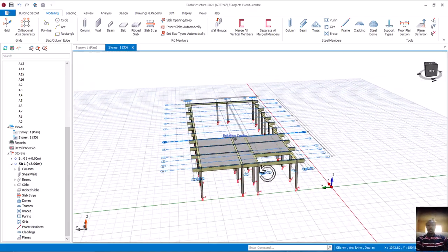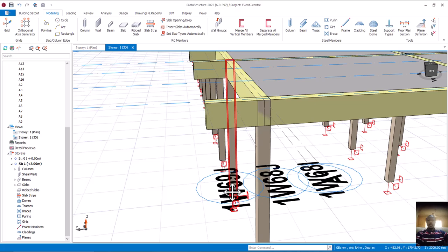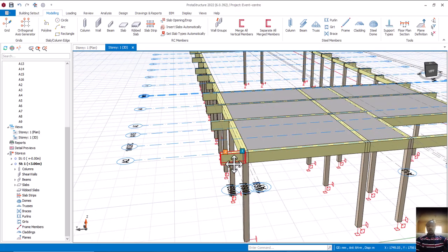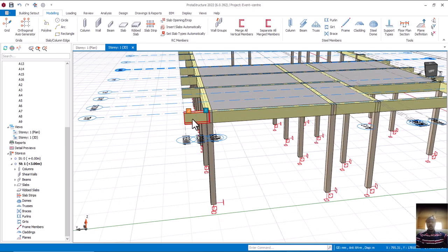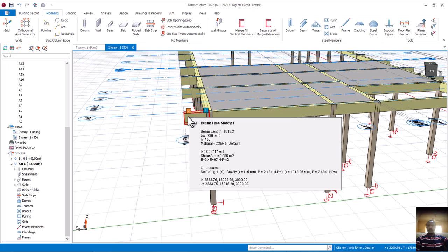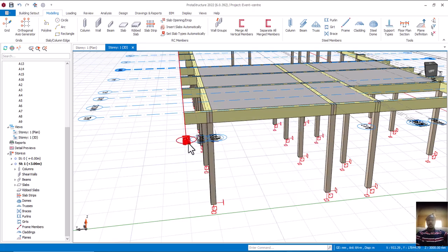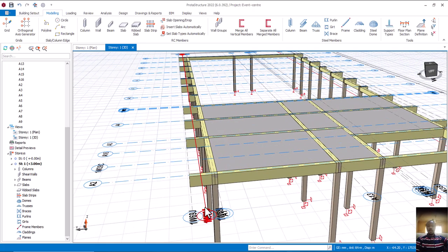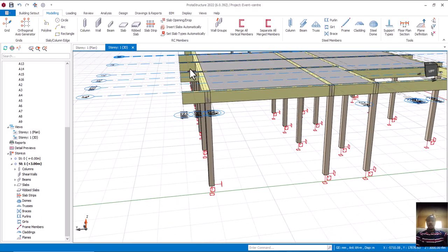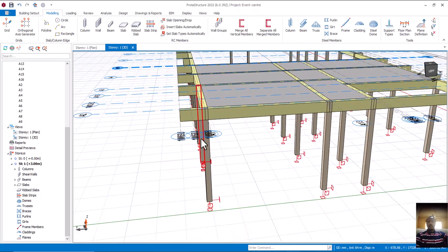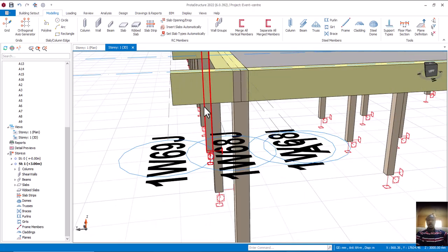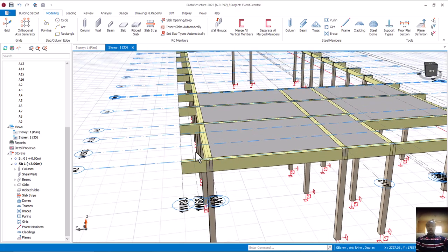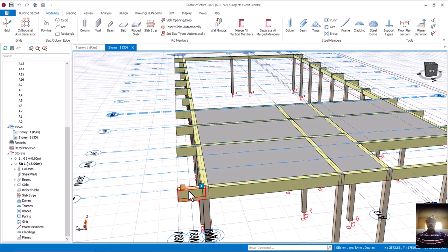Don't forget that, as I said, they are going to be raising block. Is that okay? From here like this up to this level, they are still going to raise block from here like this up. Is that okay? Because without this beam, understand, we are going to have a straight column. You can imagine the height of straight walls from here like this up without anything bridging it. Is that okay? At least with this particular column, the load is only the self weight of the blocks from here down that this place will be carrying. Then the other blocks up will be carried by this cantilever beam. Is that okay? So that is that.